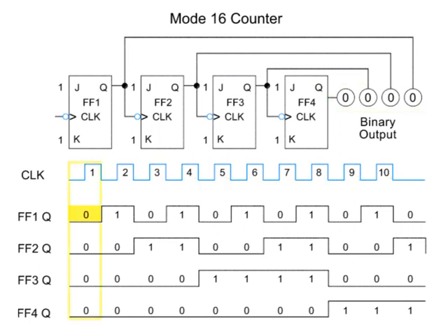As we have shown, the first clock pulse generates a binary output of 0001, and the second, an output of 0010. As the remaining pulses arrive at the input, the third pulse toggles Q1 back to 1, with Q2, Q3, and Q4 remaining unchanged, and the output is 0011.